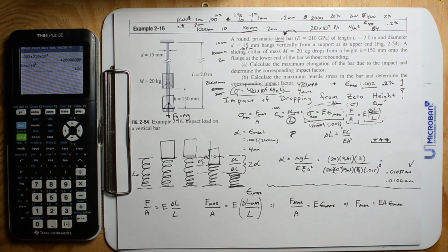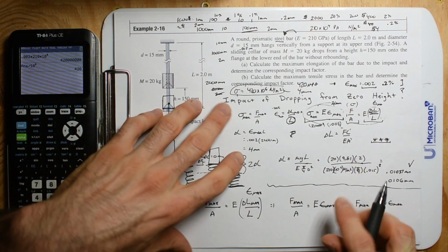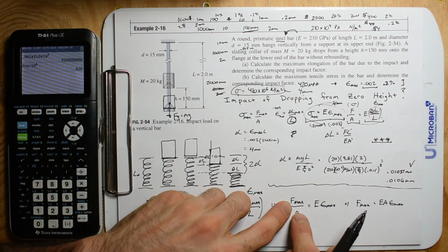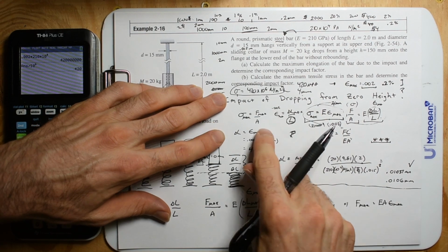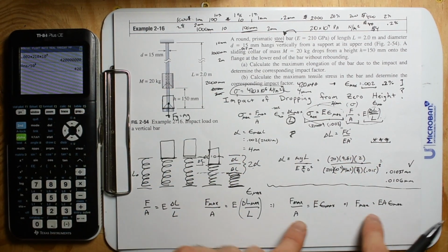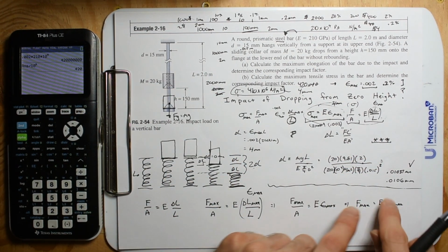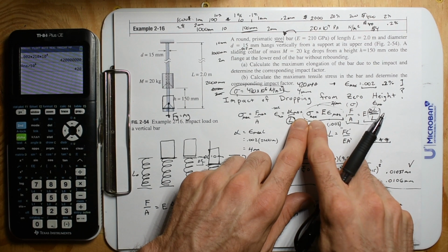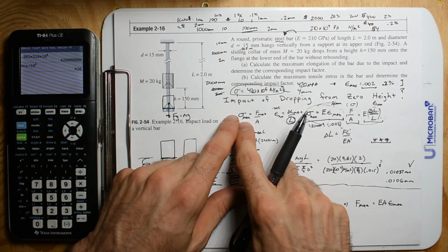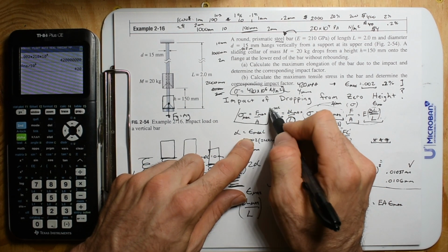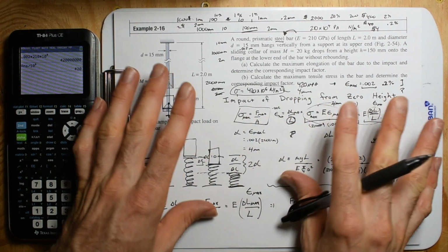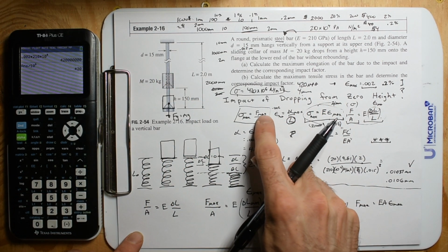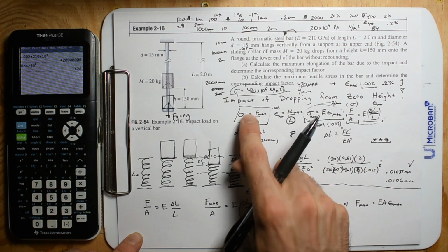But for our problem, that really doesn't help us. We really want to know what the force is. Because we have this, we don't have to do the equation all at once. We can just find, hey, what's the stress max? And now we can throw it in here and find what's the force max. Any of these equations are kind of like 3 different things. You can arrange them 3 different ways. So we're going to rearrange this for force max. Just bring the A upstairs.